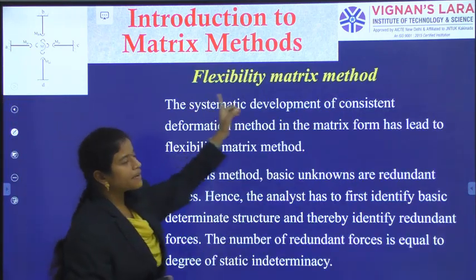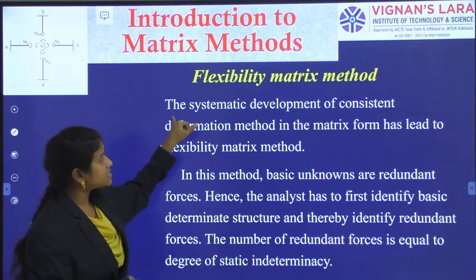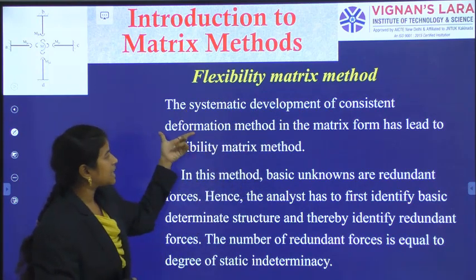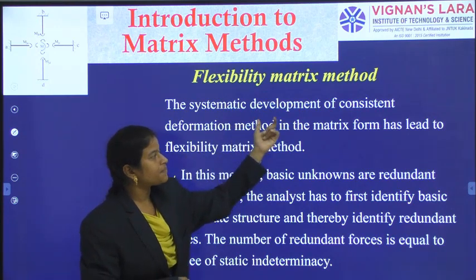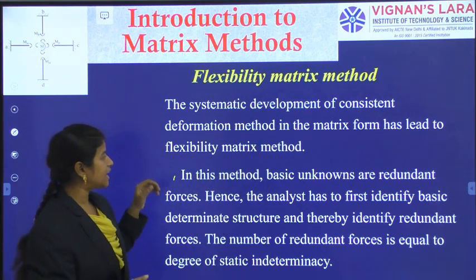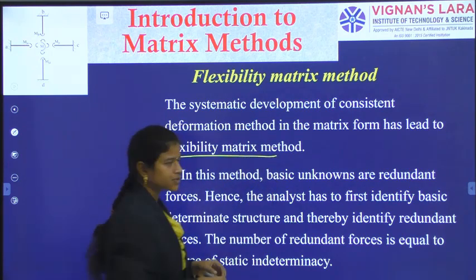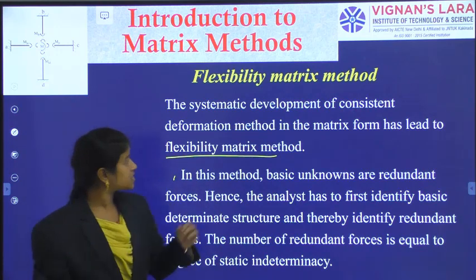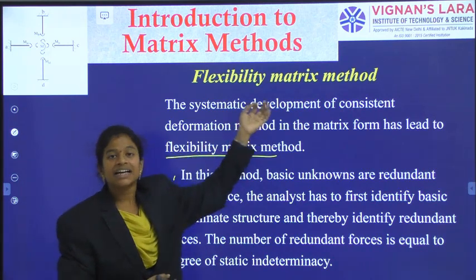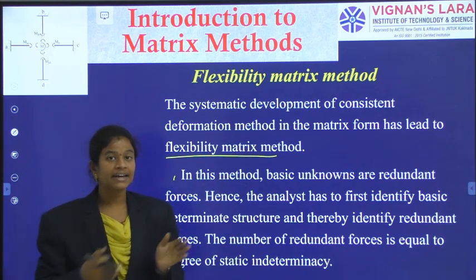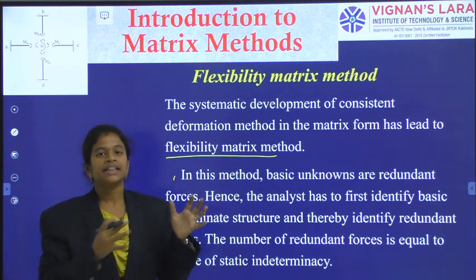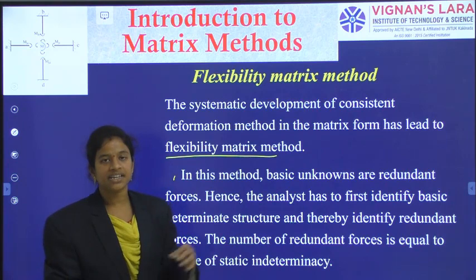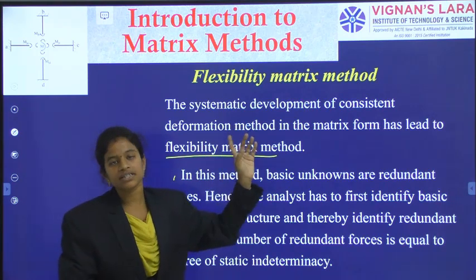Firstly, the flexibility matrix method. Okay, the systematic development of the consistent deformation method in the matrix form has led to the flexibility matrix method. So in a systematic way, when I want to calculate the deformations, okay, so the corresponding consistent deformations I want to calculate in a systematic way. So this thinking has led to the generation of the flexibility matrix method.